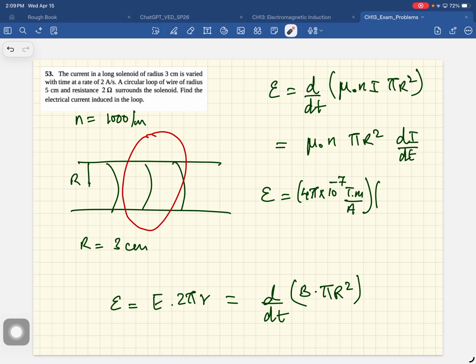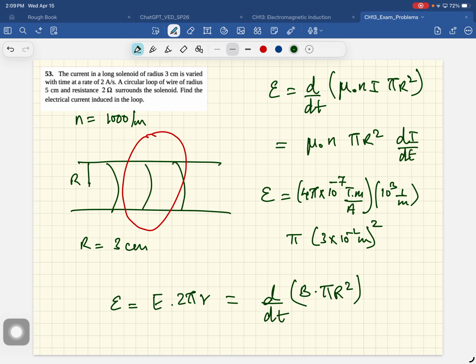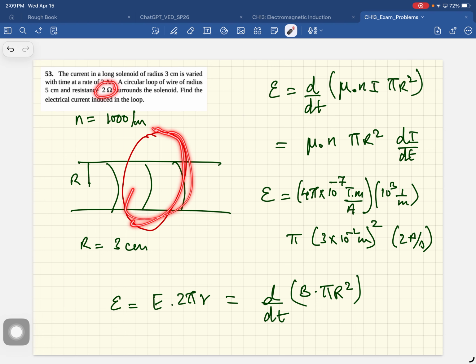If you look at this expression, as a coil turns, the amplitude of the voltage is N times A times B times omega. N is the number of turns of the coil, A is the area of the coil, B is the magnetic field strength, and omega is the angular velocity.